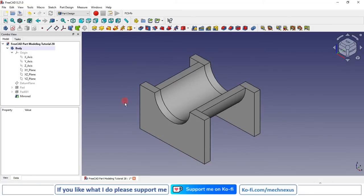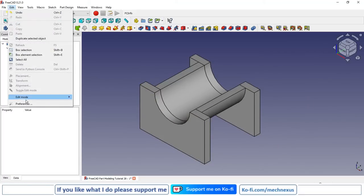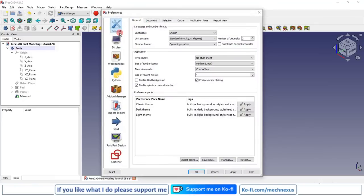So here I have opened the FreeCAD user interface and I have opened a very simple part. To customize the user interface, go to Edit and then Preferences, and here on the General tab you will see the language options. You can change your desired language from here.